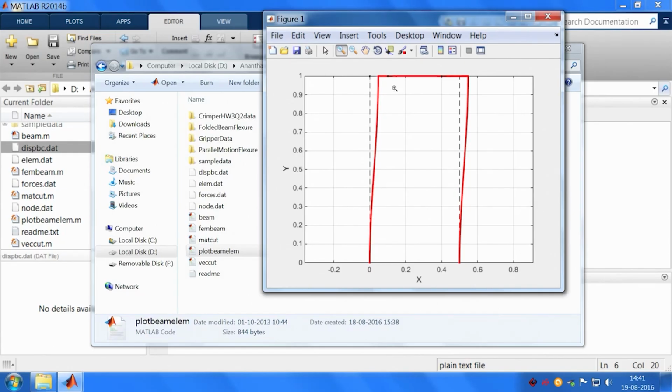And this applies to any complex beam compliant mechanism that you make up, it will show you the interpolated beam also. So, you have degrees of freedom only at the ends, but you would know the deformation at every point. Normally in any finite element software this will not be so, it will show as a straight line. If you want to see the curved one, then you have to put several nodes in between so that you can see the deflected profile, whereas if you use the shape functions to interpolate throughout the element you get a realistic picture. That is what we have done.